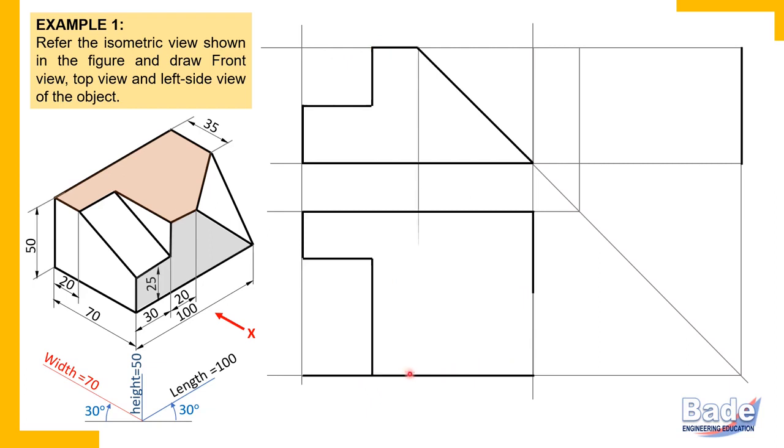20 millimeters you may measure independently here, or you may draw a projector. For smaller details, I prefer independent measurement. I avoid drawing projectors for smaller details. Okay, so this is that length, 20 millimeters. So this end we got it.